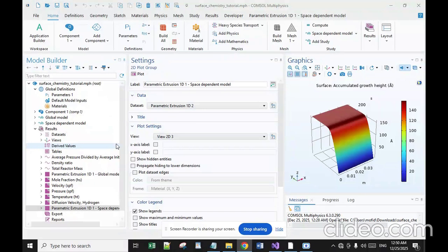Vapor phase epitaxy. The next one is photo-initiated CVD. This process uses UV, or ultraviolet, light to stimulate chemical reactions. It is similar to plasma processing, given that plasmas are strong emitters of ultraviolet radiation under certain conditions, and PICVD can be operated at or near atmospheric pressure.